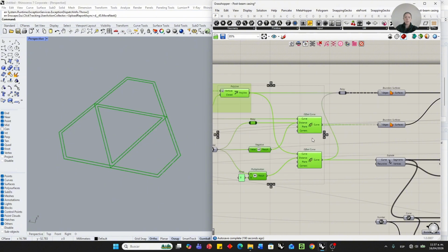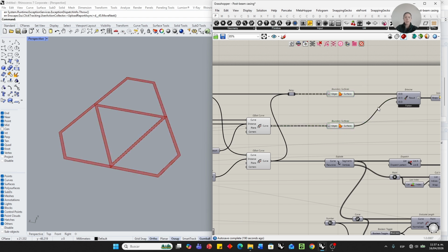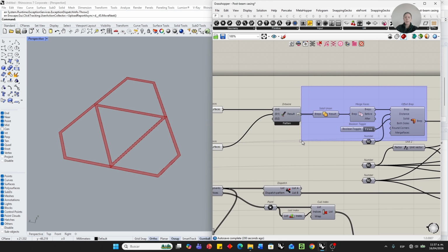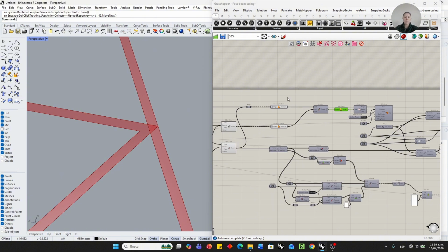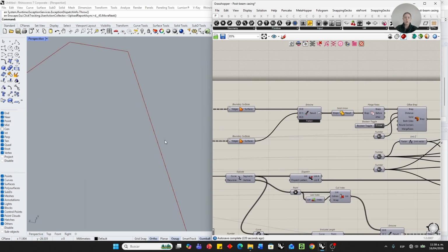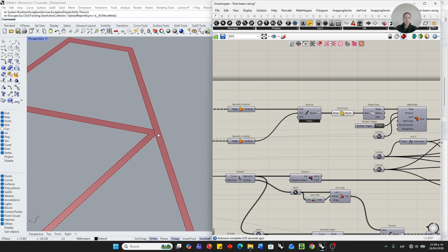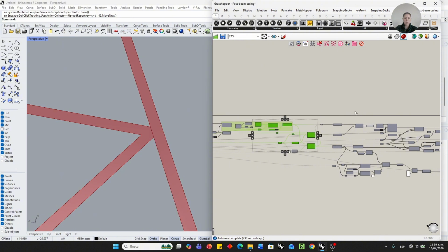When I do this, then I created the boundary surfaces on each of them, and then with this process on top, the reason why I used solid union and merge faces is because if you see right here, both surfaces are overlapping, and my vision for this script was to have everything as simple as possible, so I decided to join both of them with a solid union. I will turn it on in a moment. And now that they are both joined, I will turn this off.